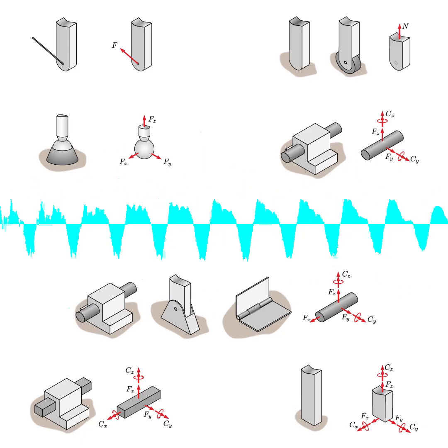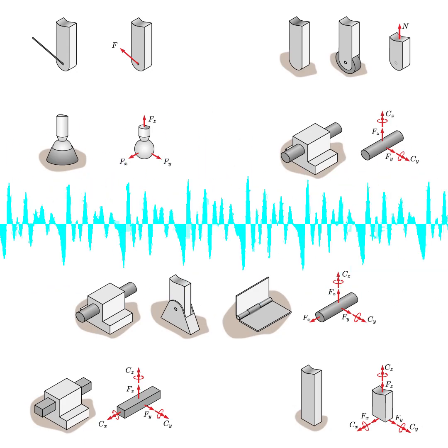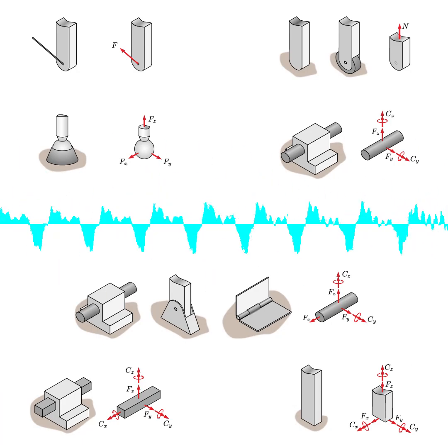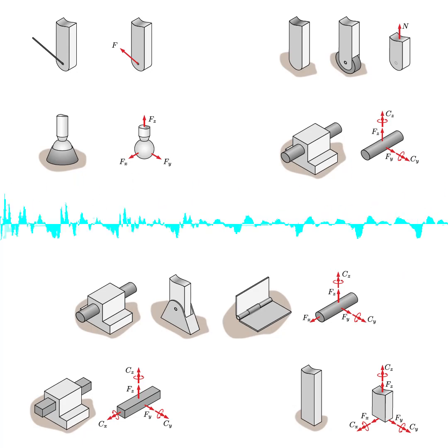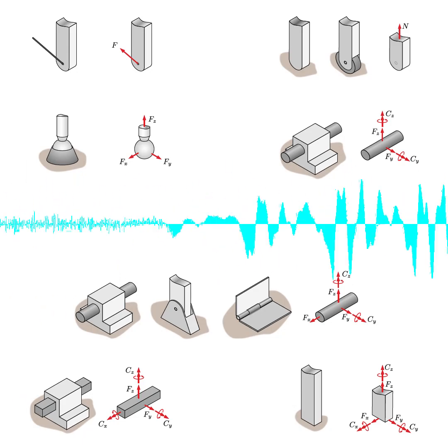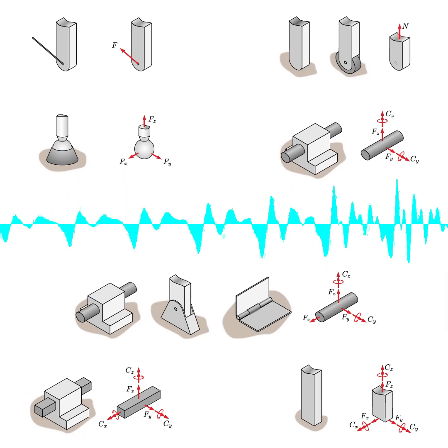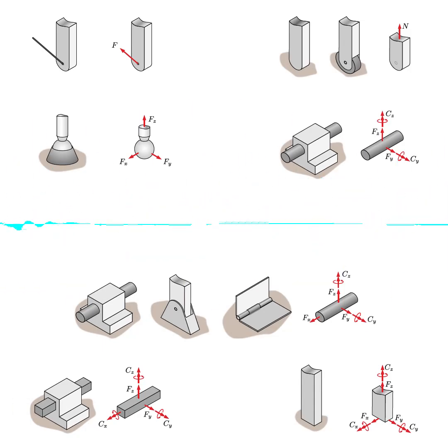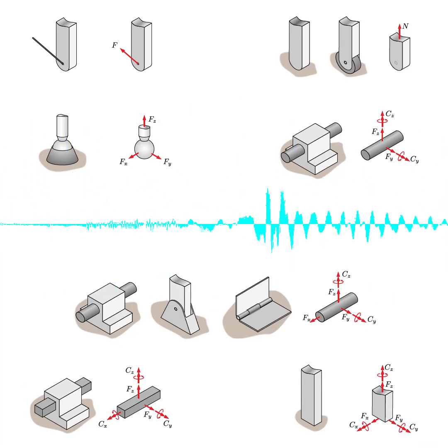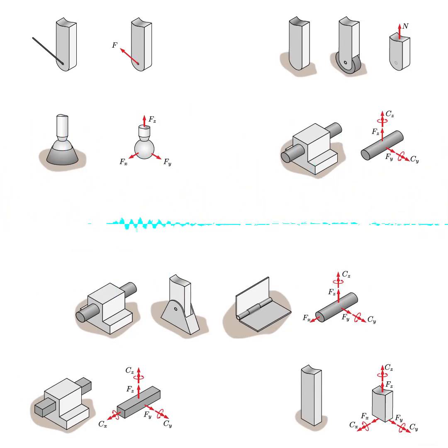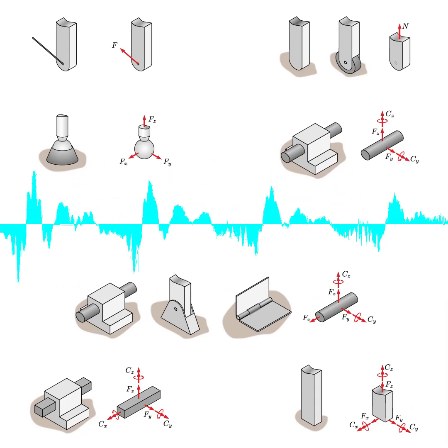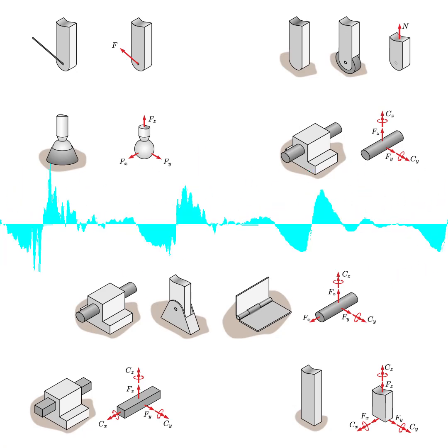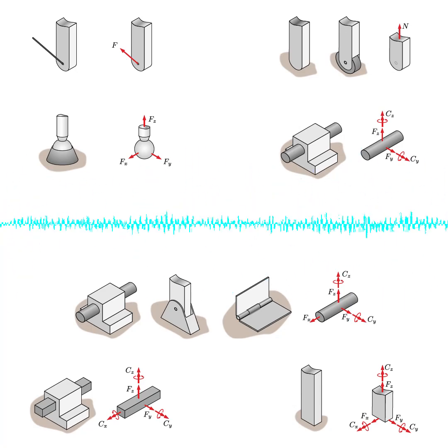Okay. So in statics, since we're dealing with things that aren't accelerating, we have 2 fundamental vector equations. The first is that the sum of all forces acting on the body must equal 0. That's often written as sigma F equals 0. Right. And then the second is that the sum of all moments about any point must also equal 0. So sigma M equals 0. So basically these equations are just saying that everything's balanced, there's no net force causing translation, and there's no net moment causing rotation.